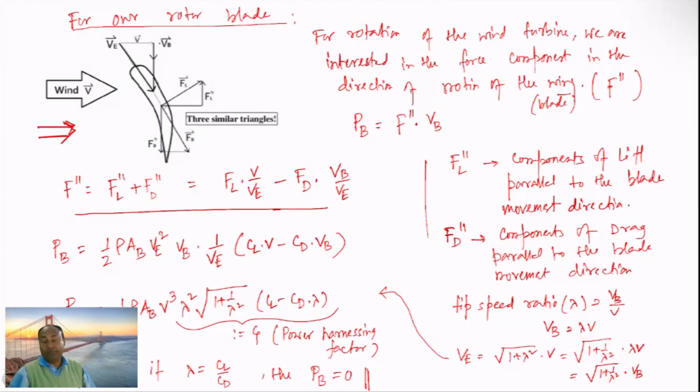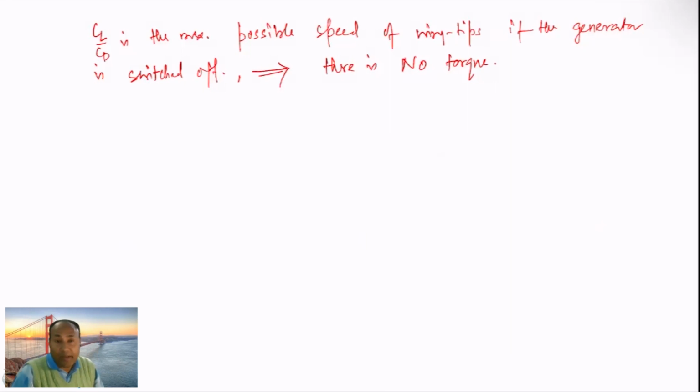So in terms of wind speed, effective wind velocity in terms of blade tip speed, and then you can estimate this mechanical power production, and that is also dependent on your C_L and C_D, and C_L and C_D can maximize or minimize the situation.